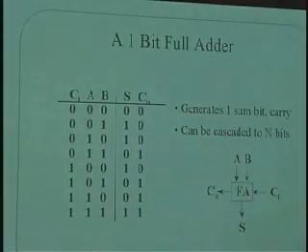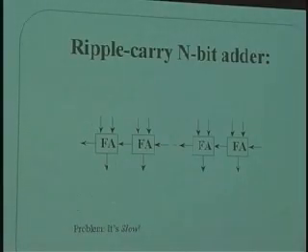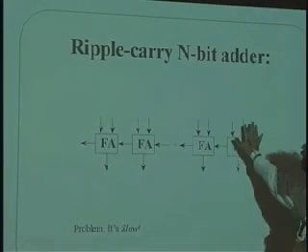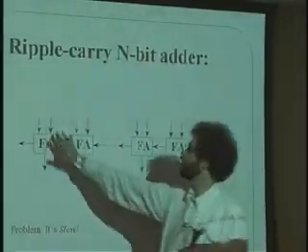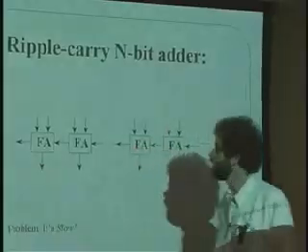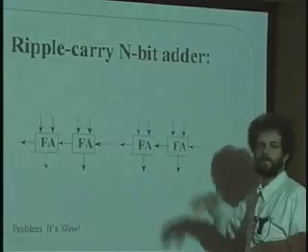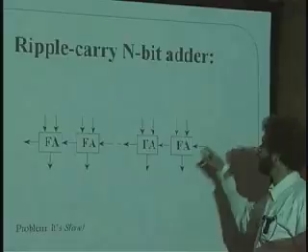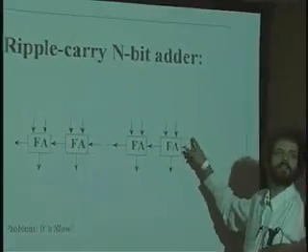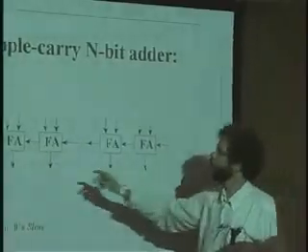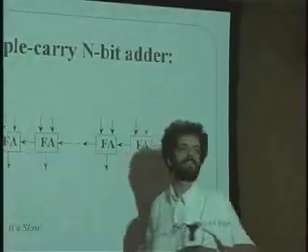Now, what you realize when you do this is that you could combine a set of full adders the same way that I just showed you there, by putting them in a chain like this, where the least significant bit is over here on the right-hand side, where we traditionally draw bit number 0. And the most significant bit is on the left-hand side over here. And if we're just summing together 2 n-bit strings, what carry in do you think we should feed in on the right-hand side here? A 0 or a 1? 0. Okay, great.